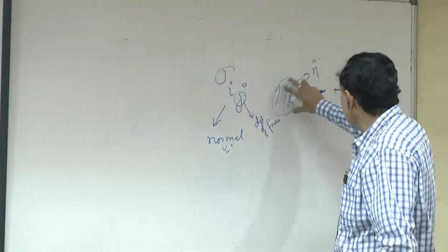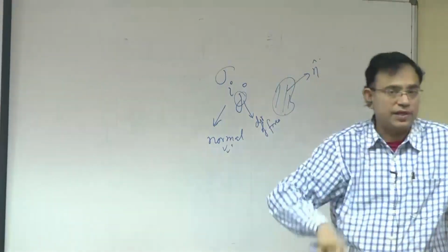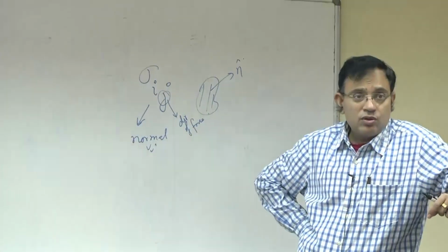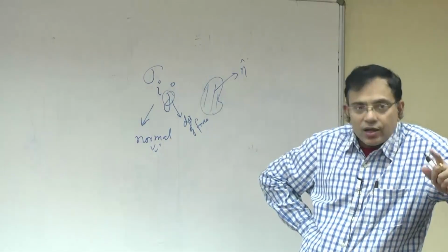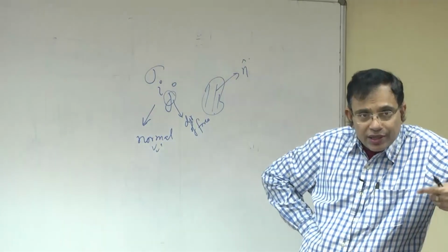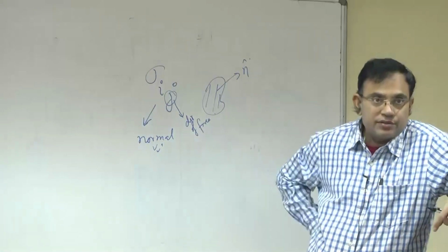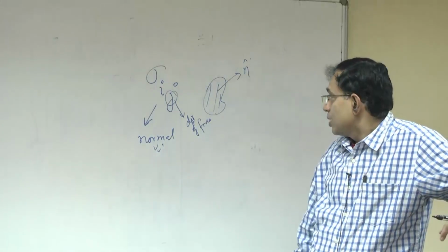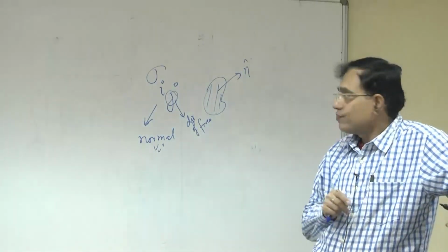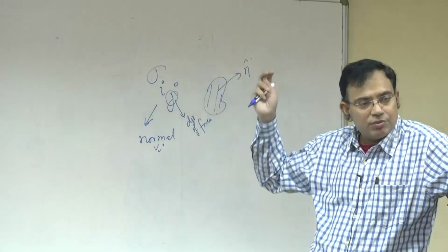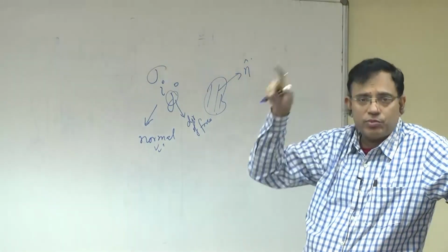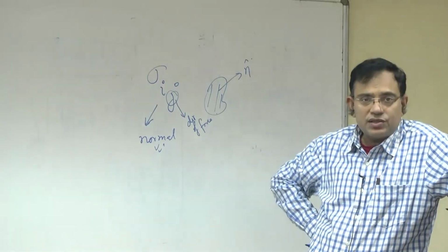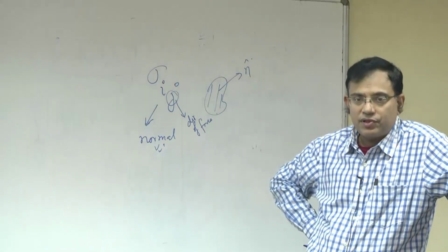If you change the direction of the normal at a given point, the force will change, because the area orientation will change. So, the force will not just depend on where you are calculating it, but also, when you calculate it per unit area, on how the area is oriented, and that is why the orientation of the area is through the index i. So, i can be from 1 to 3 and j also can be from 1 to 3. If you write it in matrix form, you can write a 3 by 3 matrix. Otherwise, it is called a second order tensor, because it requires two indices for its specification.